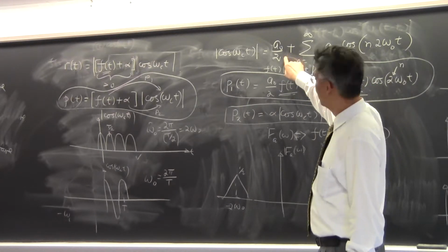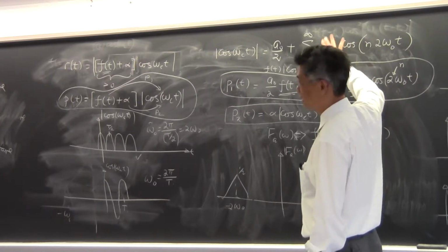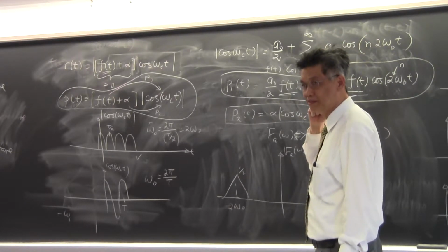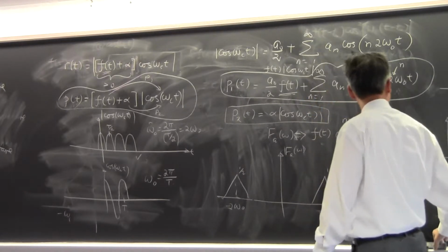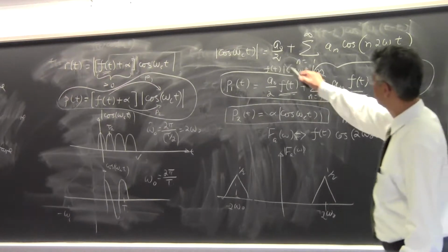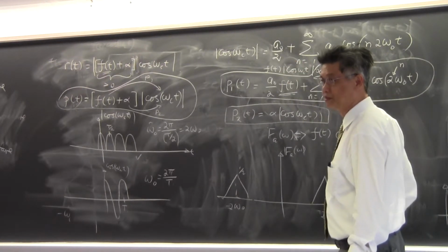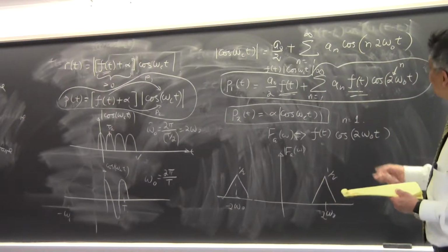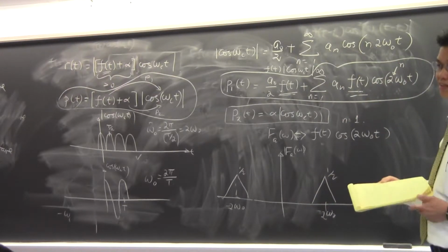I do not pick up any of these other extraneous terms because they're all producing high frequency signals. Can you see that? So I can do a low pass filtering on this signal and will pick up something that is the sum of these two. And then I can adjust its amplitude, get rid of the DC term very easily.